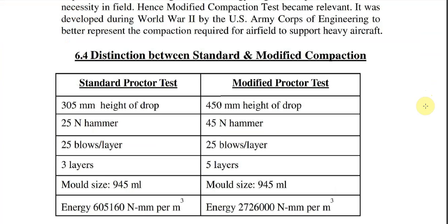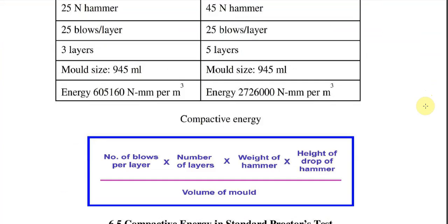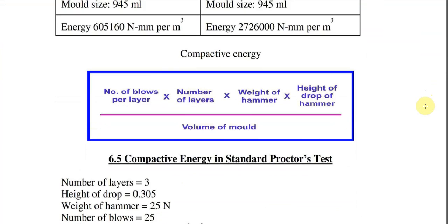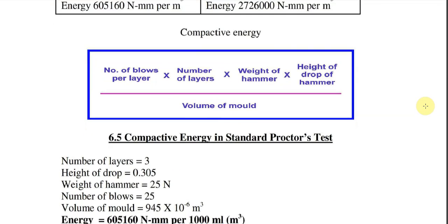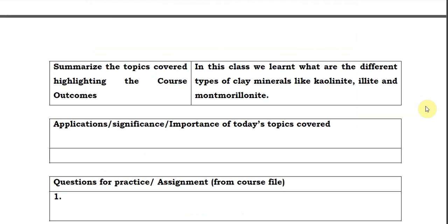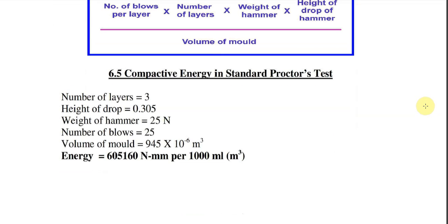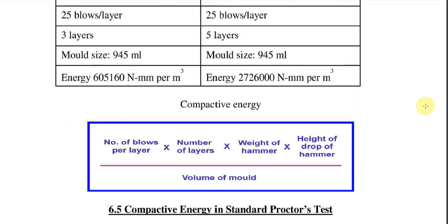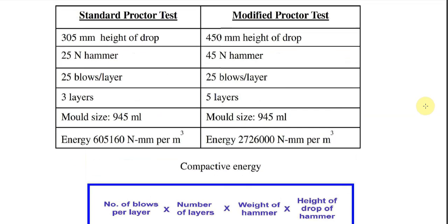That's why we are putting a lot of energy when we are conducting the compaction test. Please remember, the compaction energy is 4.5 times that of standard Proctor test.